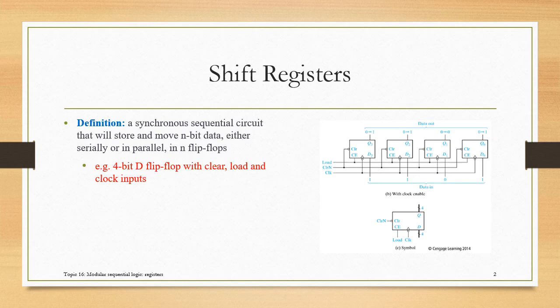Registers, in most cases called shift registers, are defined as synchronous sequential circuits that store and move n bits of data in n flip-flops. The movement of the data could be serial or parallel, depending on the design. For example, the graph on the right shows a 4-bit register using D flip-flops.